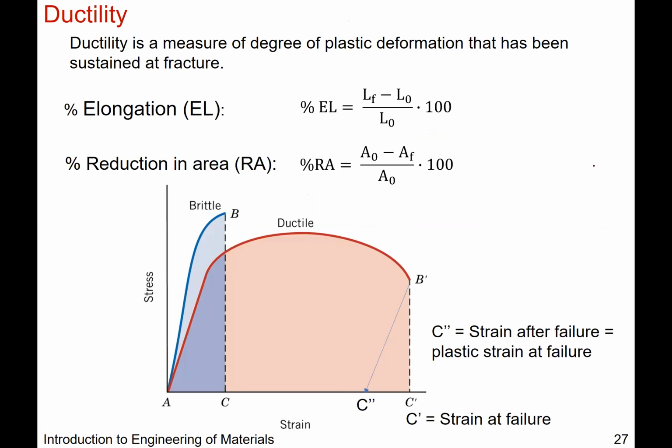So metals can be ductile. When we talk about the ductility of a material, we're really talking about percent elongation after plastic deformation, or reduction in area. What you see in the literature more so is this value, where we measure the final length minus the initial length L naught and normalize by the initial length itself, multiplied by 100. So that's the percent elongation.